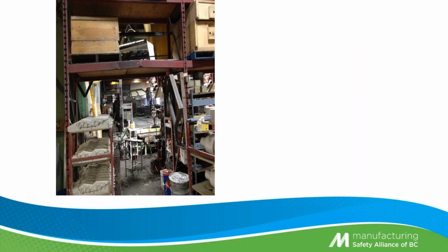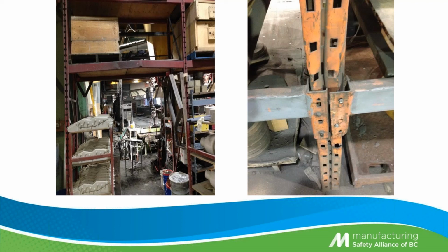So here I wanted to show a bunch of pictures that I've recently come across. Here we're looking at racking, and this is one of the big new standards that are coming forward, and this is something that we can easily find on a workplace inspection. Obviously, a forklift or something has dinged this because they've lifted it up and bent the main horizontal piece. In the second picture, we can see that it's obviously been hit quite a few times and they're trying to just screw it together.